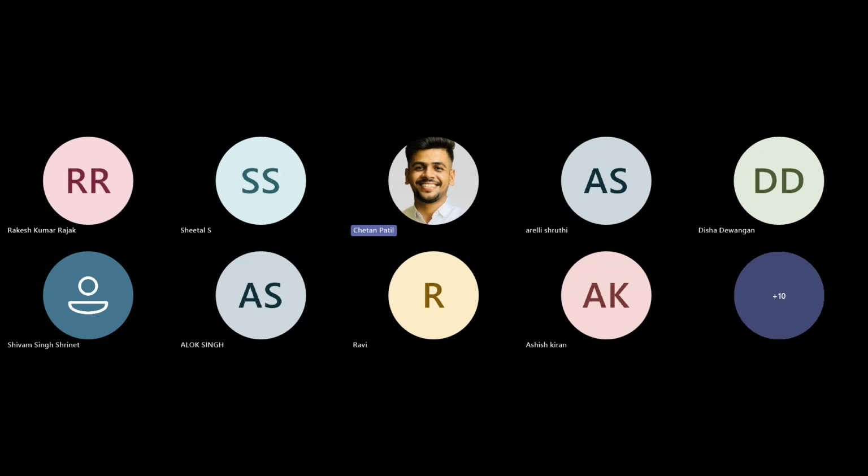Initial time step only decides where your simulation should start. Minimum and maximum are the two parameters between which the incrementation of the load will be selected.